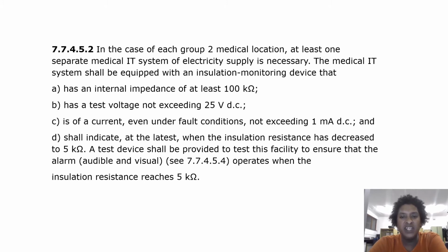A test device shall be provided to test this facility to ensure that the alarm, audible and visual, operates when the insulation resistance reaches 5 kiloohms.